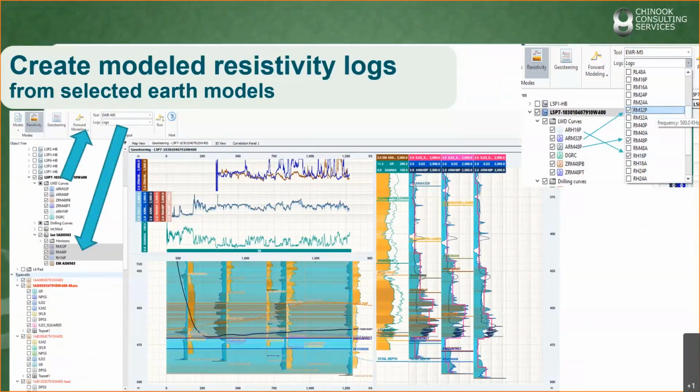It's a separate submodule, and it's used to generate simulated resistivity curves based on a theoretical response of specific tools used in the well when we drill through the earth model that we created. Now, what goes into these calculations are well trajectory, angle of incidence, bed thickness, tool specifications. These are all parameters that go into the computation, relatively complex, I'd say. The generated simulated curves that we'll see here will be compared to the actual LWD response. And let's see here how this would work.